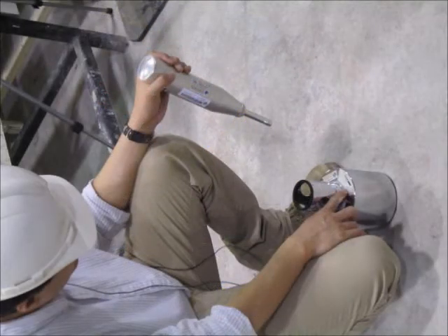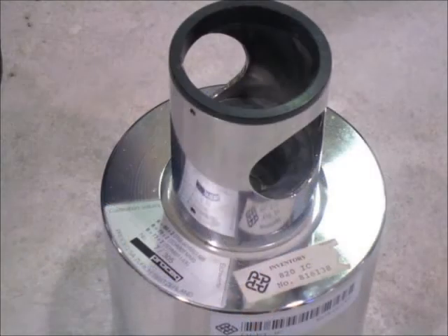It is intended to measure the depth of the carbonated layer near the surface of hardened concrete by using a pH indicator or phenolphthalein.